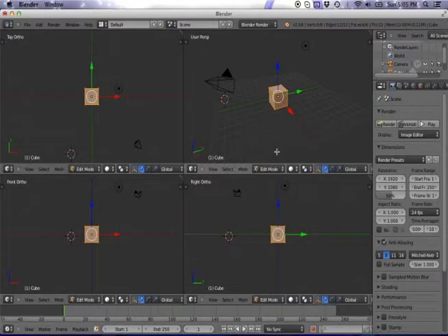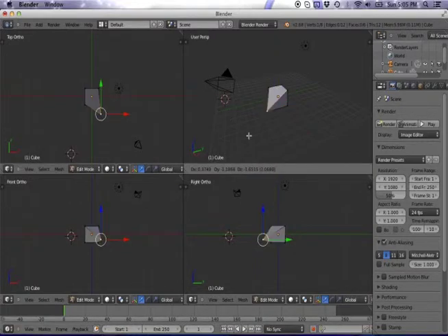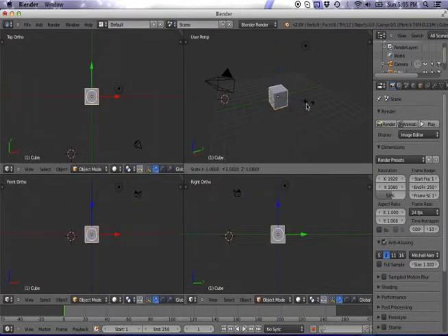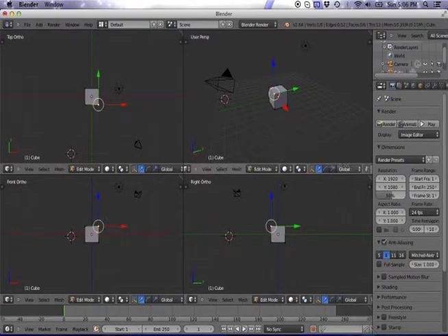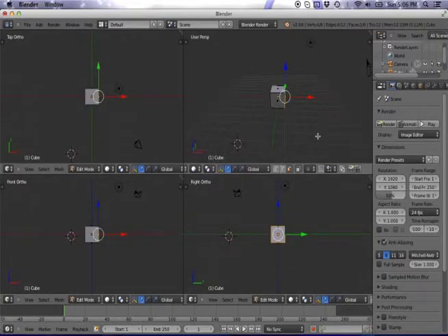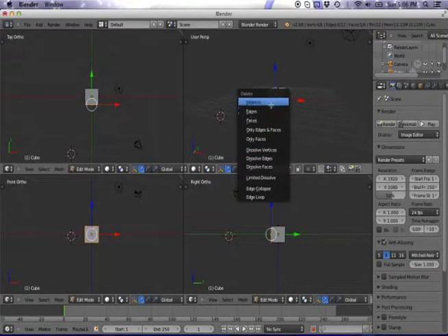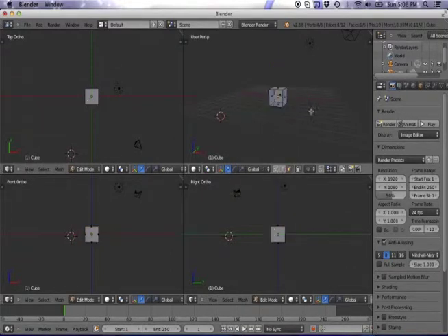First, to edit an object, you take it into edit mode, then you can control the vertices directly. If you press G, you can move it around. If you press S and R, that is scale and rotate, respectively. In edit mode, you can choose here to change between controlling edges, faces, and vertices. You can press H at any time to hide something, and then Alt-H to bring it back up. Pressing X lets you delete vertices, edges, or faces.